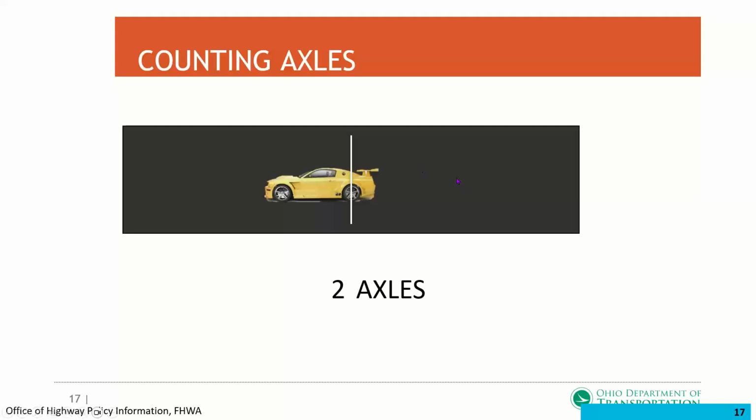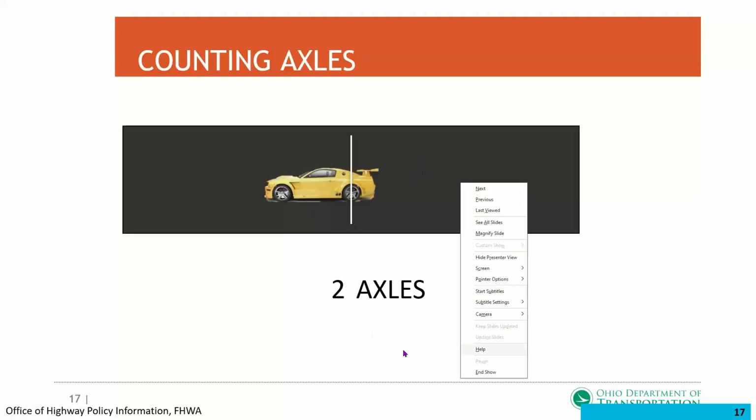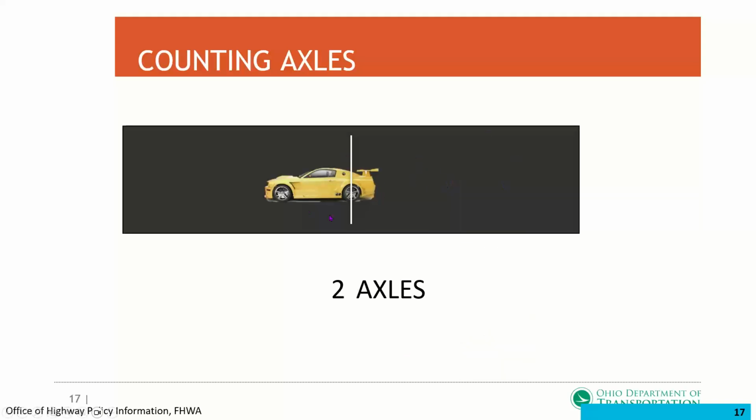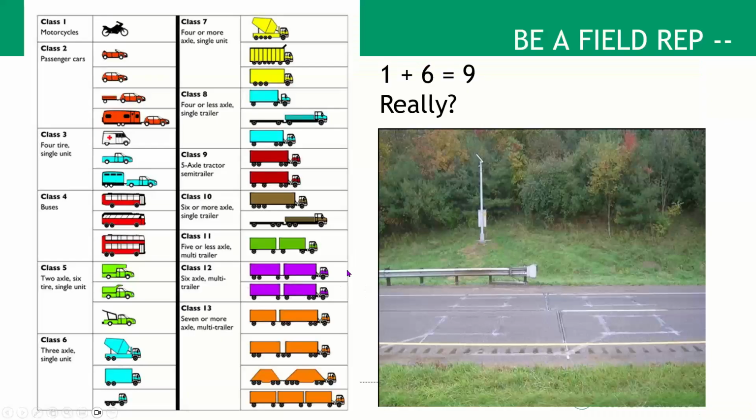So we have that loop here, then this piezo, then this loop. We knew exactly when this vehicle came into this loop, piezo, loop array. We know when they came. Now we know exactly how many axles they have. So now we can tell, in that case, it was a car. It had 2 axles. We know exactly how fast it was going. And so we can now classify that as a car.